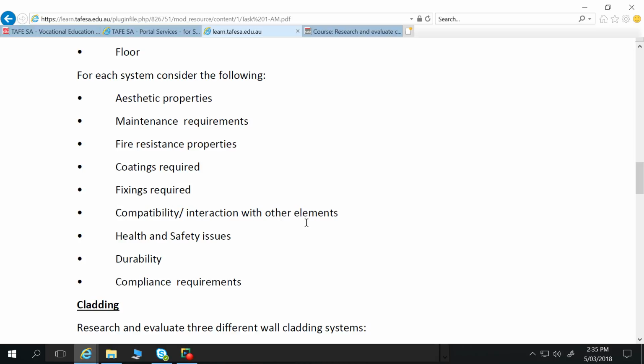Yep. Basically, the easiest example is a ship. You don't have just one earthing point because it'll actually cause corrosion at one point. Yep. And they'll have also on the boat what they call sacrificial anodes. So they're attachments to a ship where all the corrosion will go to one point. They can just undo it, put enough bits on, and it saves the actual hull. It's in hot water services too. Yeah, got them in hot water services. Yeah, we put them on tanks we build as well, sacrificial anodes.